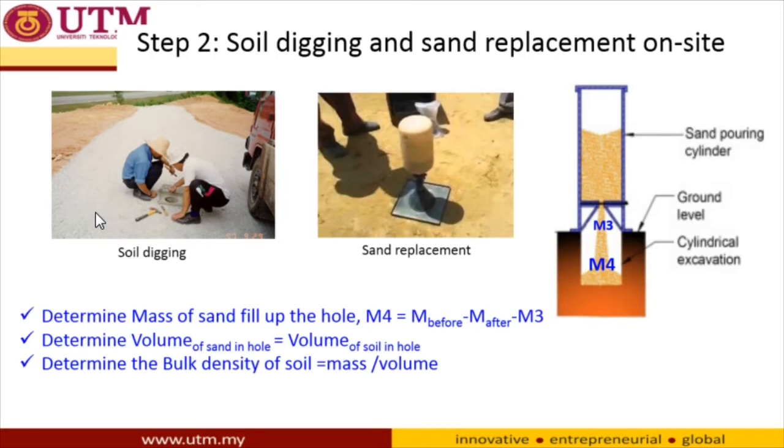Now, let's assume that the soil is ready for the sand cone test. First, a hole of 4 to 6 inches is excavated manually after placing the metal tray on the ground. The soil should be kept in an airtight container and later determined for moisture content.